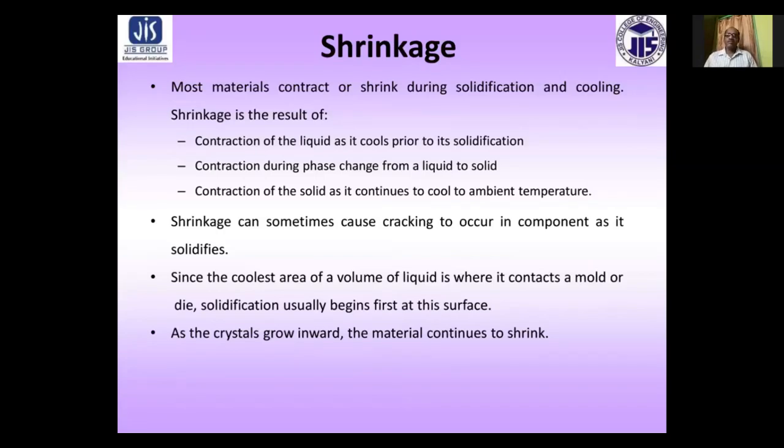Next is shrinkage. Material contracts or shrinks during solidification and cooling. Shrinkage is the result of contraction of liquid as it cools prior to its solidification, contraction during phase change from a liquid to solid, and contraction of solids as they continue to cool to ambient temperature.